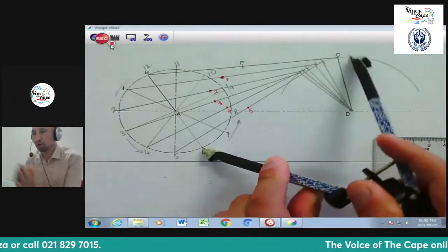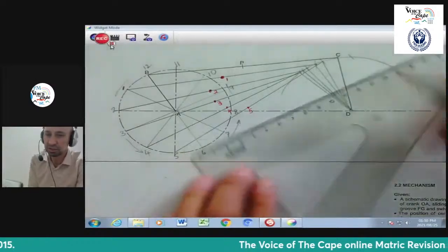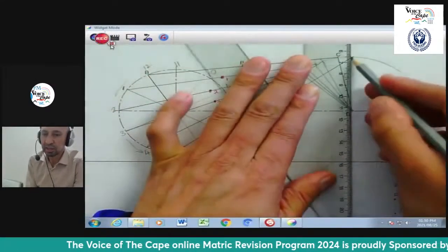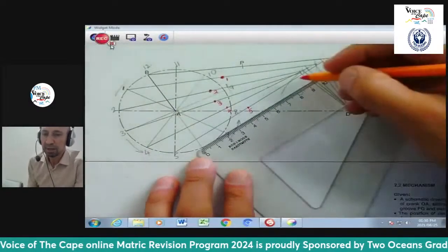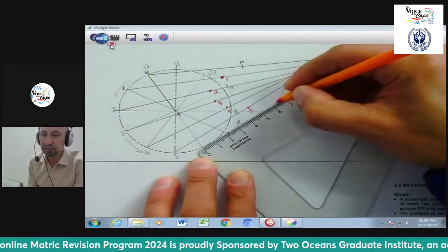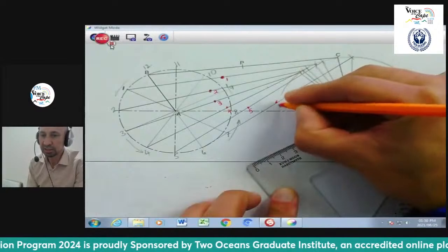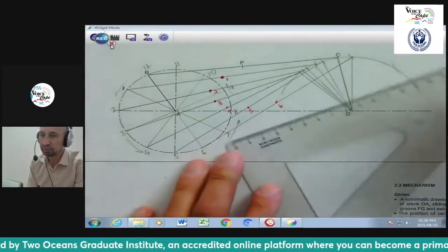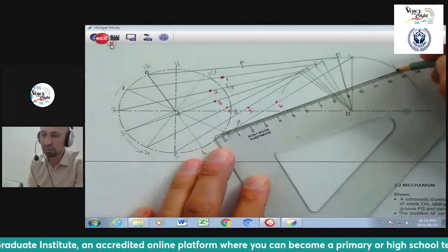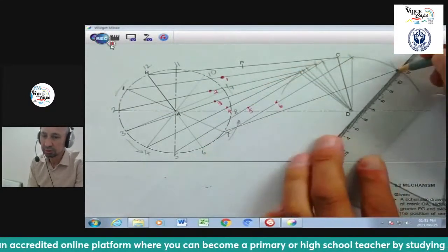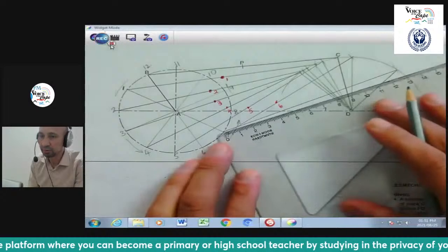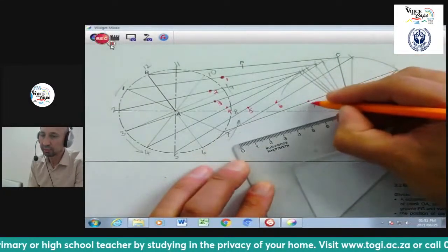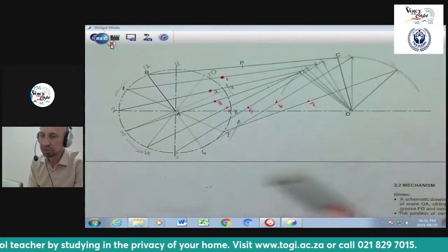Now it pushes that rocker more to the right because it's coming to the closest side, or the right side, of my circumference of motion, which is this side here. And you will see there I connect 6 with that point there and draw down to the base of my rocker. Number 7 is from there to the marked point, and then measured off on the line number 7, which is 63.